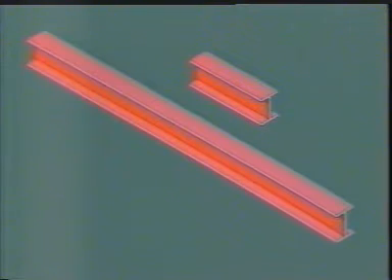For a very stocky beam, the plastic moment is significantly less than the critical moment and instability does not occur. For a very slender beam, the reverse is true, and the beam will fail by elastic instability. The response of very stocky and very slender beams is quite clearly defined and relatively simple to analyse, at least in an approximate manner. However, many practical unrestrained beams lie in the intermediate slenderness range, where the effects of elastic instability and plasticity interact.